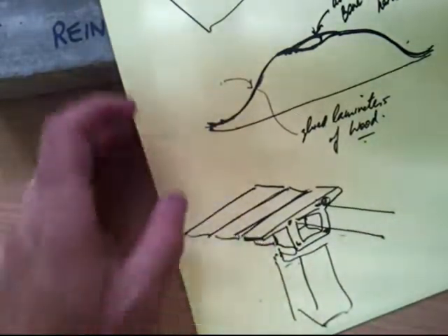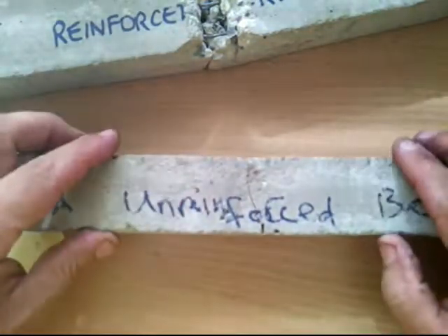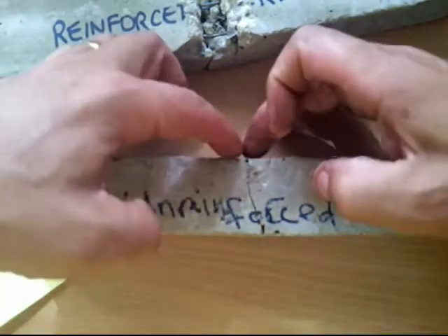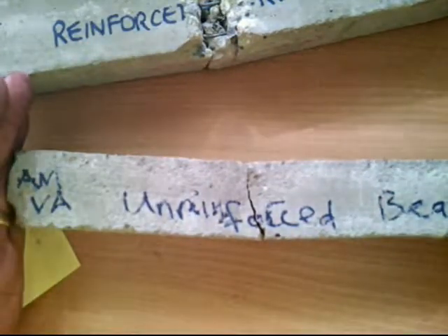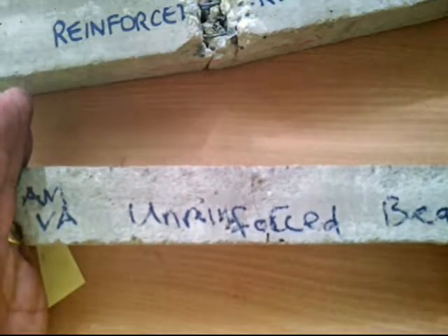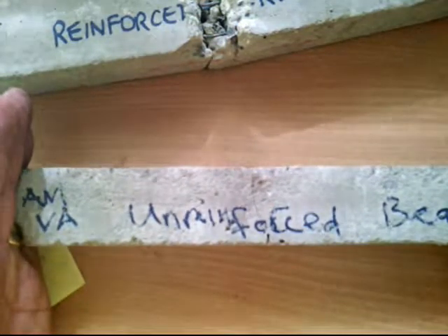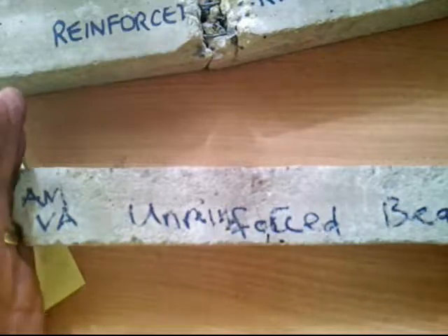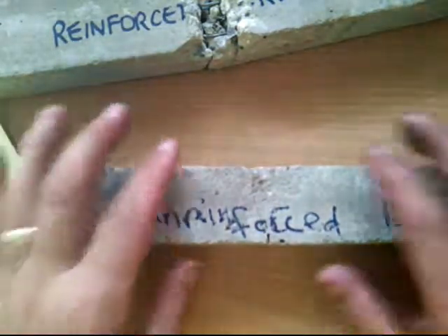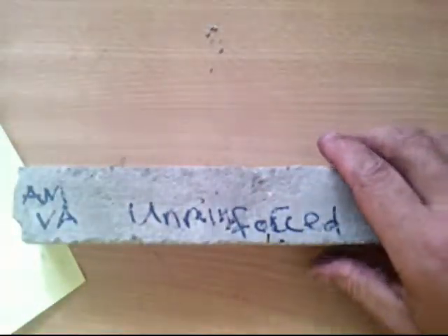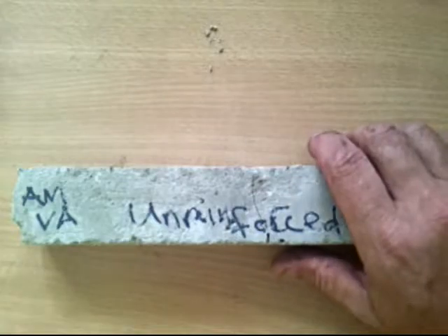Now, one of the advantages of post-stressing too is that it does help to close any fractures. Remember, concrete's a brittle material, so when it starts to crack, for loads coming where my fingers are pointing, the bottom starts to open up and a crack opens up. Well, if there's pressure from my hands on either side, the crack closes up. And before that crack can open, that compressive stress has to be released, has to be overcome. So you can see the advantage of post-stressing.